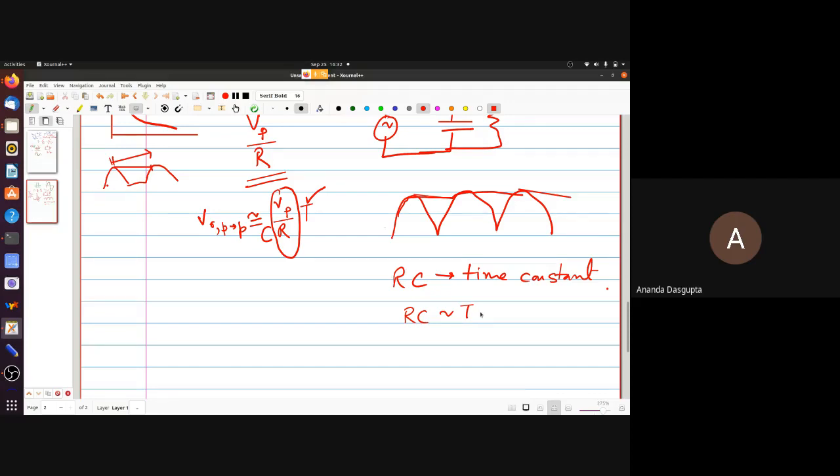So if your load resistance is of the order of a kilo ohm, you would not use a capacitance smaller than a millifarad, because a kilo ohm times a millifarad, farad times ohm, is a second. Kilo ohm times a millifarad, the kilo and milli cancel each other out, it's again a second. So when you design a rectifier circuit, you would have to design it keeping in mind what kind of capacitor values and resistance values you will use. So typically you would have a rather small ripple factor, so this is a pretty good calculation.